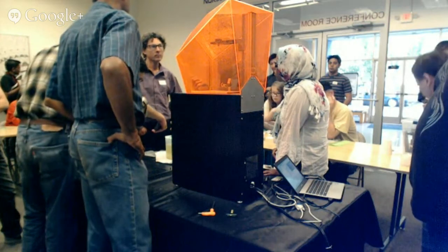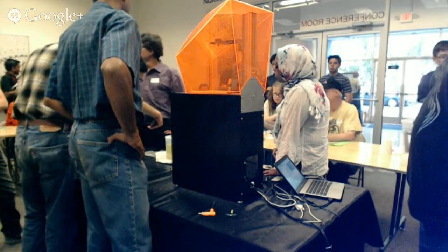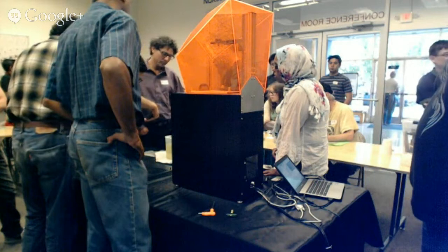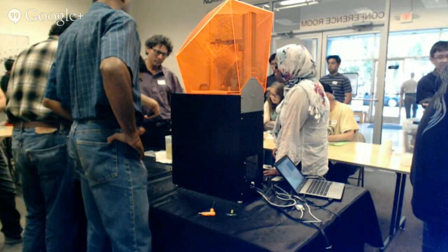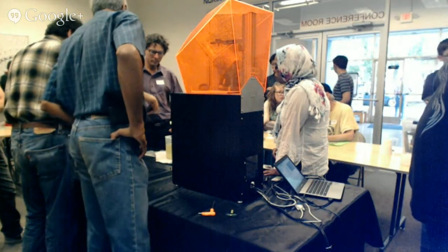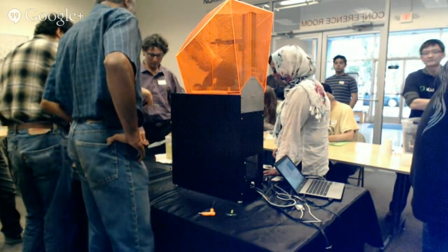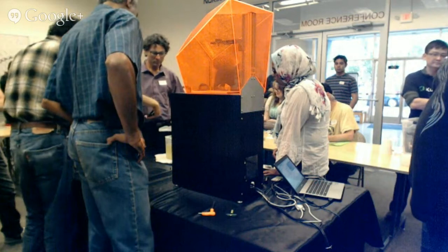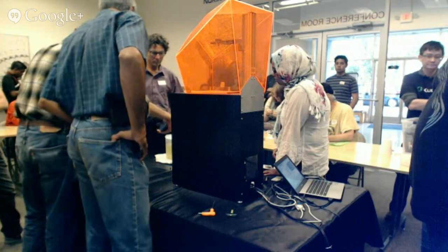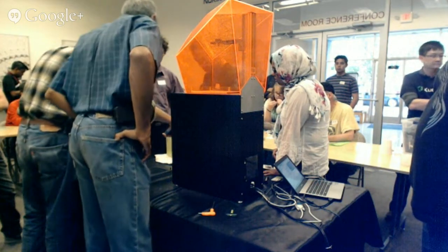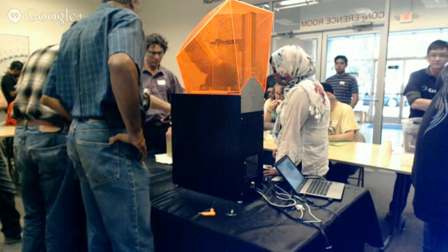You can either leave it off at the side. If you have a gap, like this part here, which has a bunch of stilts, light shining in here is going to go through. That's the amount we call overcure. And the amount of overcure you have is dependent on the opacity of the resin, and the opacity of the resin to specific wavelengths, particularly